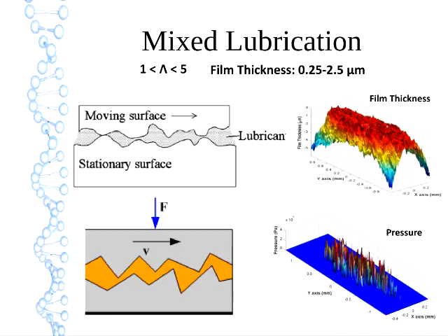Here we also have some schematics on the left-hand side, and you see that you have a lubricant in place between the surfaces, and you've got roughness, and in some places that roughness is causing the surfaces to touch, whereas in other places the surfaces are being separated. So you've got intermittent contact, and you're not too far away from actually getting the surfaces completely apart in some cases.